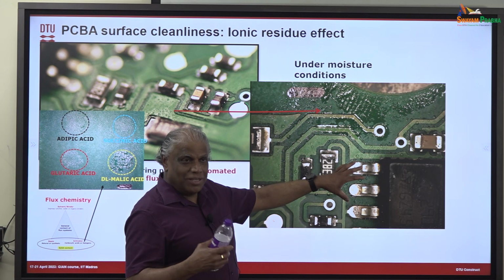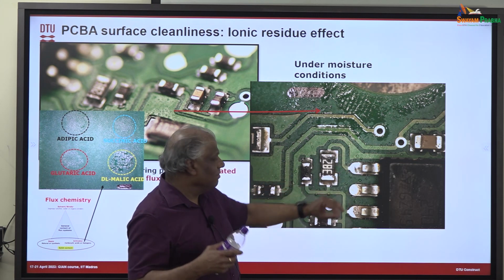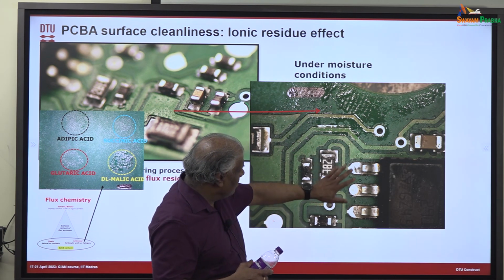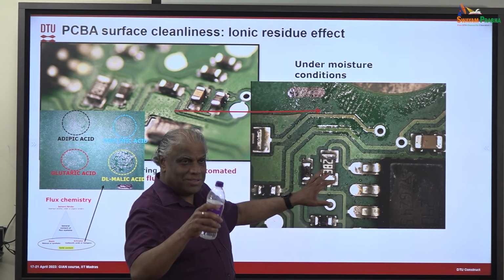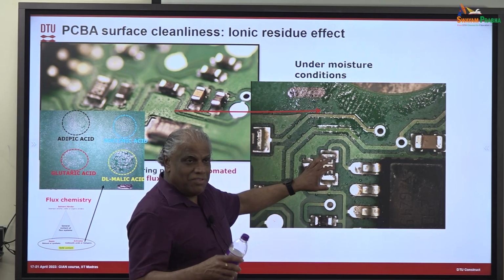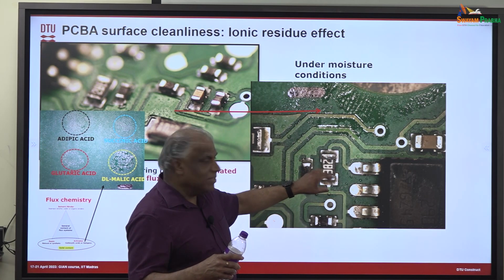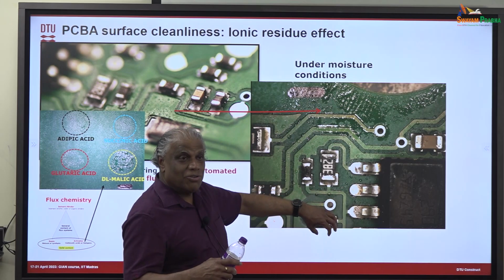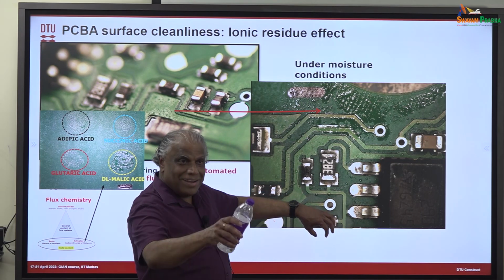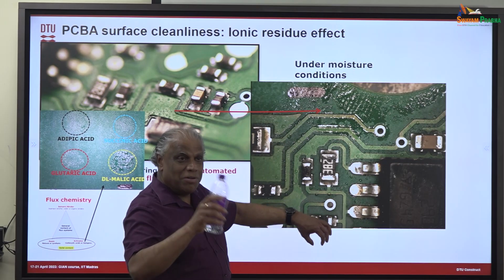So in the circuit, they can say that this area water film is forming, which means that the circuit will assume, if you give the electrical property of that water film, there's a parallel resistor here. If there's a capacitor, there's a parallel resistor over the capacitor. And that circuit will be able to analyze what will be the implication of that.